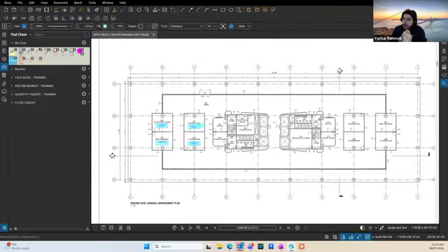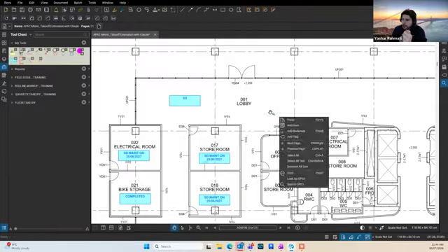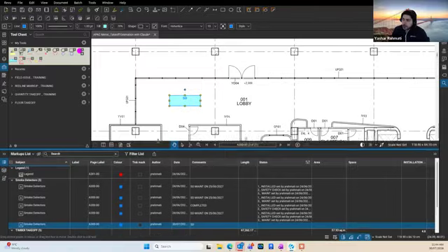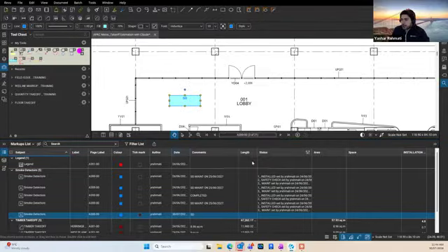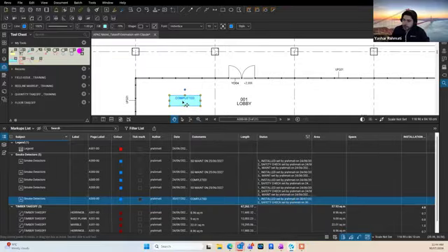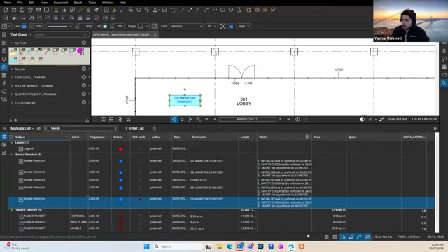A designer places a smoke detector in the right location. Once it is located, when someone on site completes the installation, they need to change the status from installation completed to scheduling the maintenance, and all of them are stored in the status box. So as an example here, the first step is to jump into the smoke detector and say, okay, we installed that. But after that, we need to make sure that we run a safety check. Once the safety check has been completed, we also have to make sure that we schedule the maintenance, which is scheduled for 25th of June 2027.